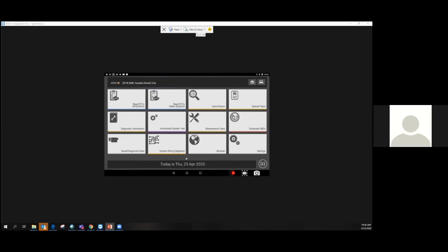Sure. What's the difference between a dynamic calibration and the drive cycle or test drive that you mentioned earlier? They're not the same thing, correct? Yes. So a static calibration, and a lot of shops may have already seen this, or at least seen stuff online, is where the vehicle is literally static. It's parked in a designated bay. It needs to be a level, flat bay. What surrounds that vehicle is really important because that camera can pick up on objects. So you want a designated bay without too many objects around the vehicle. Blank walls are important. The lighting needs to be correct.